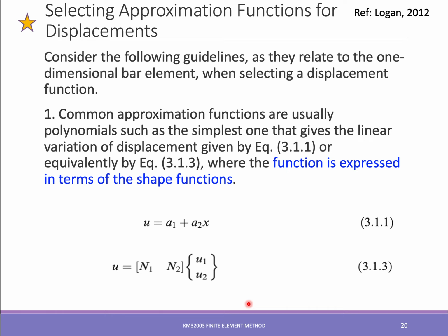So that is the idea of how you can solve it using a bar element instead of the spring element. The only difference is that you have to use the parameter AE divided by L, instead of the spring constant or the spring stiffness, okay?